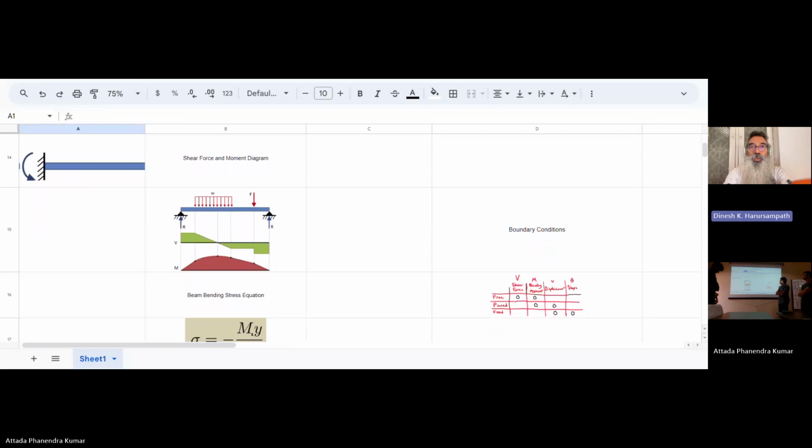You can't show both, because at the support, you can't apply a moment. It doesn't make sense. You have to apply the moment at the tip or somewhere else along the length of the beam, and the support resists that moment. So if you're showing the reaction of the support, then you should not show the support itself. It becomes a free body diagram. So you can't show both the hashed and the circular arrowed quantity together.